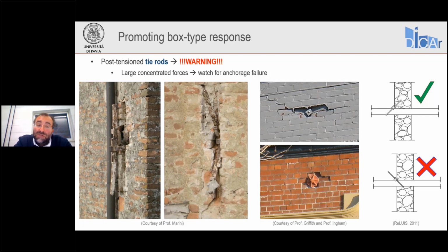Now, when you don't use a wide bearing plate, but these other systems, which are narrow, be careful on the orientation of that anchor, because it needs to engage either the transverse wall or the slab. The situation at the bottom right is not acceptable, because in that case, you see only half of that anchor system is bearing against something.